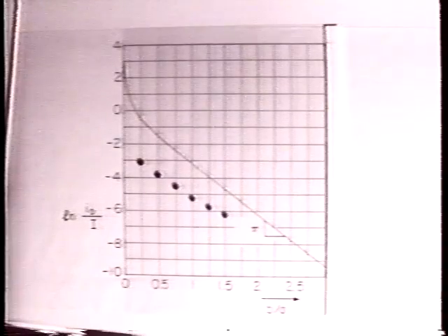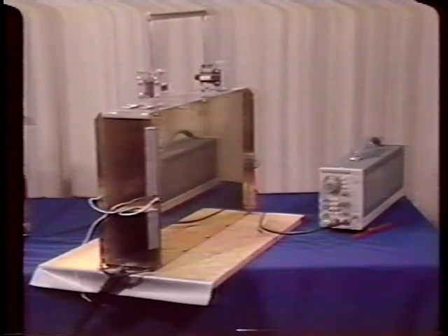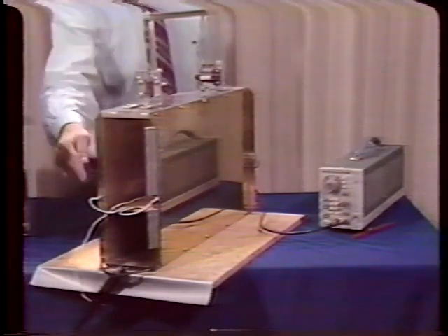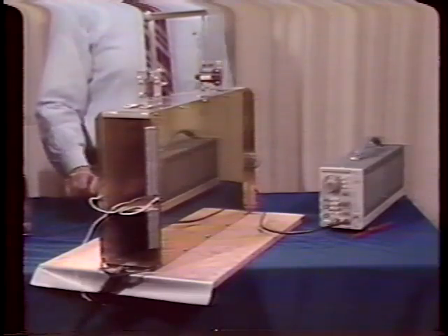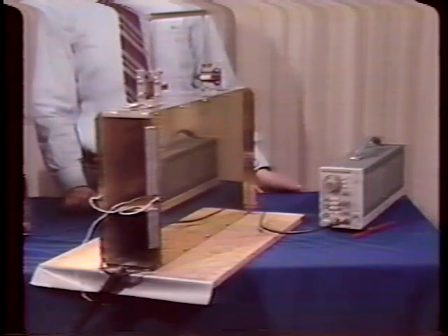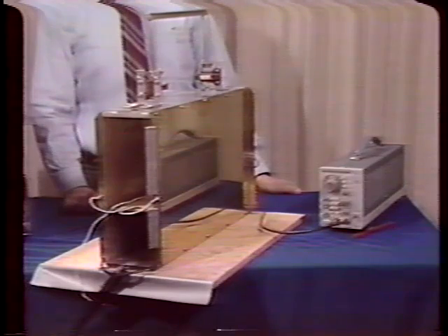Here are some other values which we've measured. The current I sub 0 in the lower electrode does have the correct variation with spacing between the electrodes. However, it's displaced downward from the predicted curve by essentially a constant factor of 8 or 9. The main reason for this discrepancy is the flux linked by the wires used to provide the return current paths. The rate of change of this flux makes an addition to the measured terminal voltage that makes the normalization current I larger than it should be.